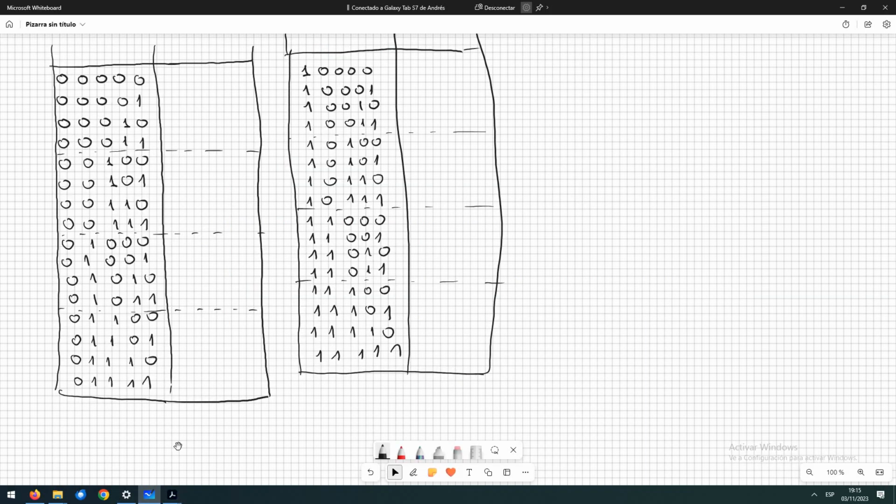We have 5 inputs: the switches and the car sensors of road A, B, and C, which are going to be 1 if we have cars, and 0 if there are no cars, and the three of them work the same. So we have a function of 5 variables.